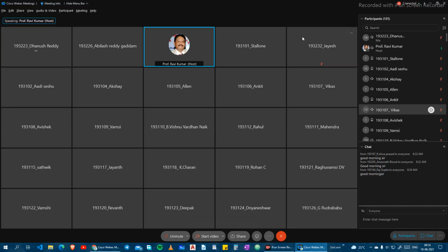Whatever power is developing in the power stroke is a high power. A few percent of the power will be transferred to your back wheel, and a few percent of the power is supplied to your flywheel. The flywheel stores the energy, and it will be utilized for the remaining idle strokes. That's why initially, if you want to start the engine, you use the kick rod or the battery. Initially, you rotate the crankshaft for suction purpose.